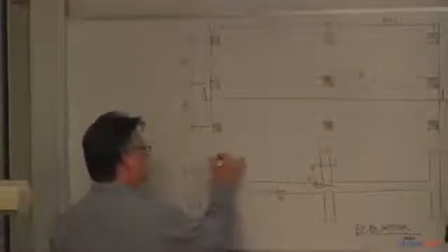So here's the column input. The fixity just means the far end fixed, which, when I drew this, is fixing the end of the column. If I wanted the far end pinned, what I'd be doing is doing this, allowing that to rotate freely. The code says for equivalent frame analysis, you shall take the far end as fixed as long as it can be, or you're allowed to take it as fixed. So that's what the F is there for.